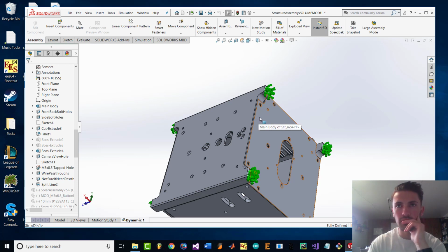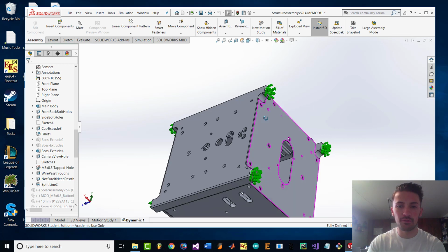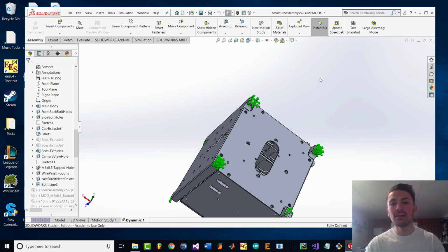And then when you delete a concentric or a tangent, you can click and move the part around and it'll be able to move everywhere. Redefine that constraint so it fits together, and do it as soon as it breaks. Because what I've noticed is when I've gone through and did 4 holes for multiple parts and then 8 holes for another, I was like, constraints are building up, I'll get to that later. But then when you get to the later, you have like 20 constraints all broken, and as you drag the part around, everything's moving everywhere. It's hard to remember where the holes lined up. So as constraints break, try to fix those.